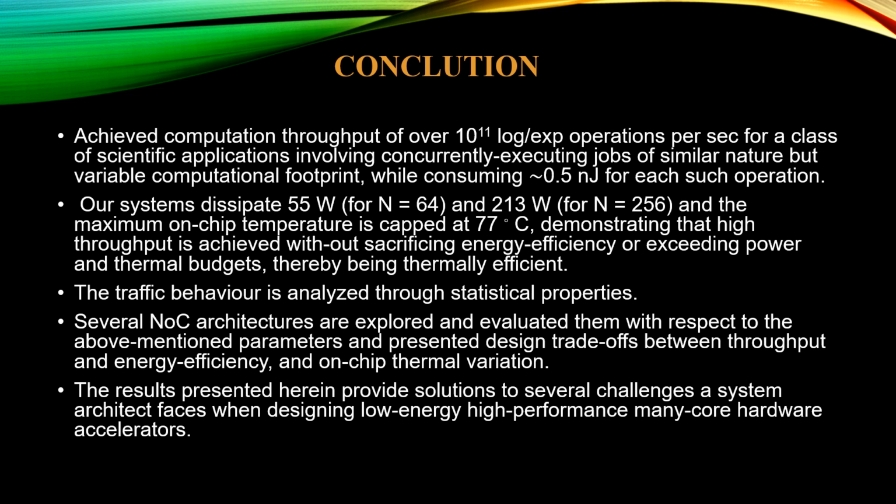And we have obtained a computational throughput of over 10^11 operations per second. And here we have used logarithmic and exponential operations. That is why it is mentioned as 10^11 log or exponential operations per second. We also found that each operation is consuming approximately 0.5 nanojoule of energy.